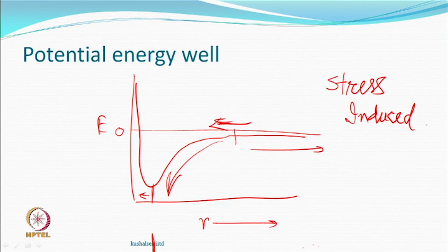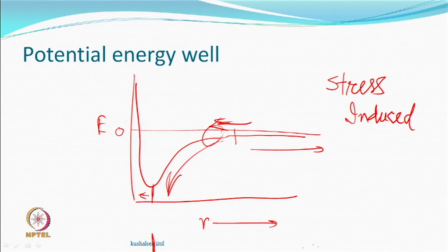Stress induced crystallization: you have done something and therefore the molecules have come together now, and hopefully, if they happen to be somewhere here, then this process will be automatic, they will finally themselves want to be there. But if suppose the temperature is very low, then you do the drawing at a little higher temperature, allow mobility. That means you facilitate it, or then we had another thing called heat setting, thermally induced crystallization.